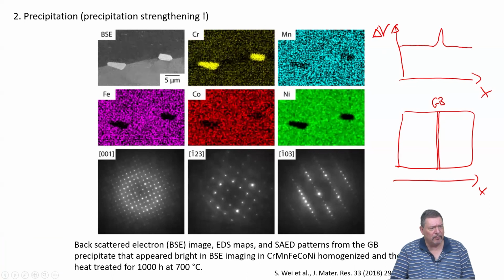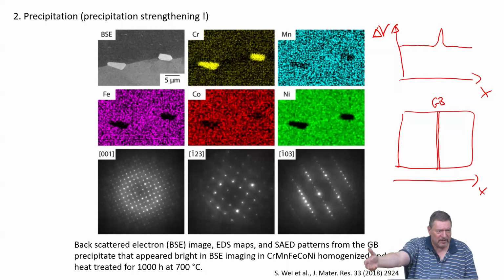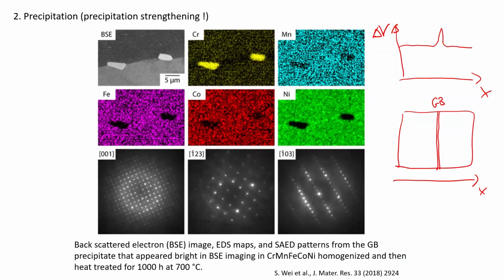So with each grain boundary, you have the so-called linear grain boundary expansion. It's a parameter measured in meters or so, but it basically signifies the additional excess volume associated with this planar defect. More volume means diffusion can occur more easily, but more volume also means any foreign element can go there more easily.